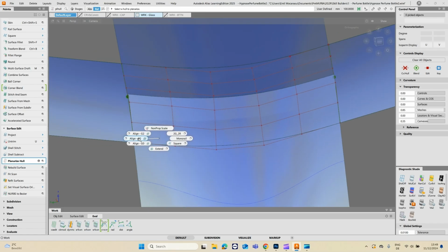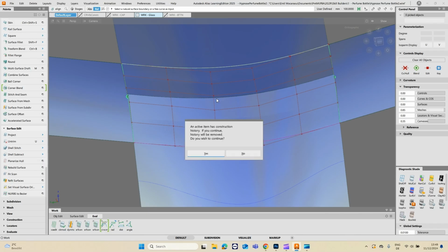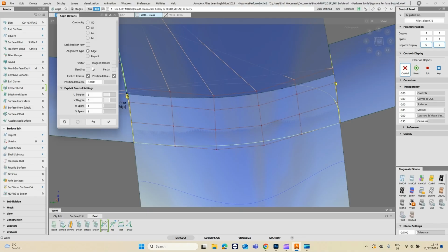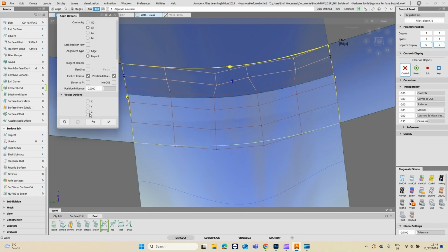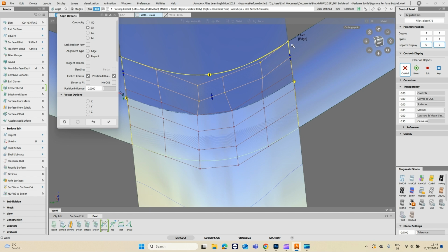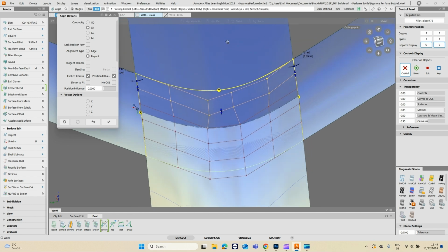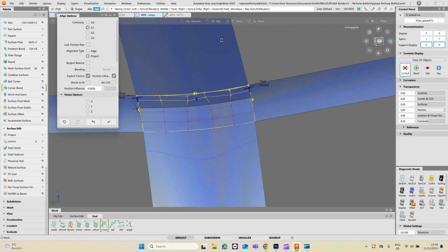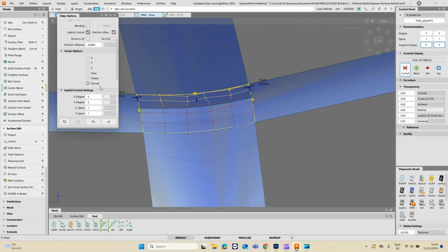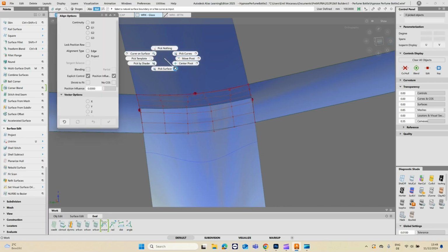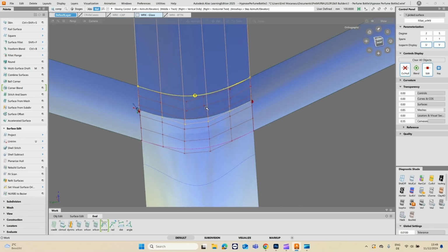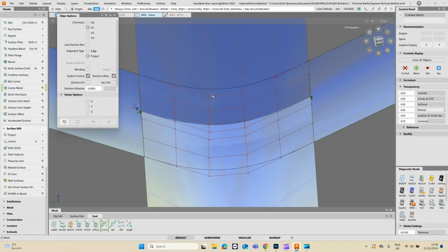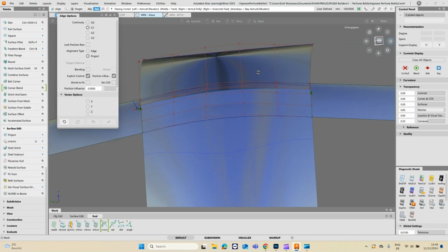What I will be doing now is aligning that radius to those surfaces by projecting it. So normal to the surface, turn off edge, I'll refer to that because I don't like the way it's looking.